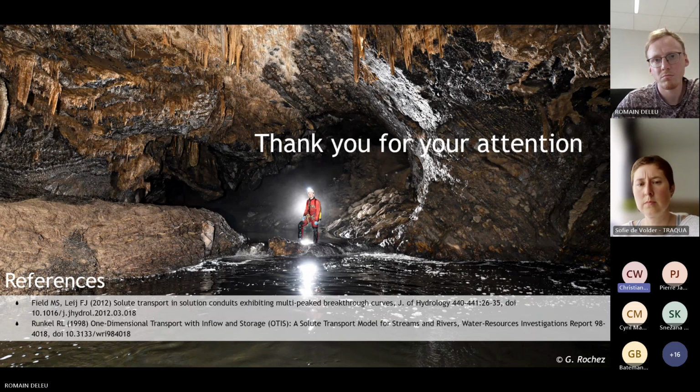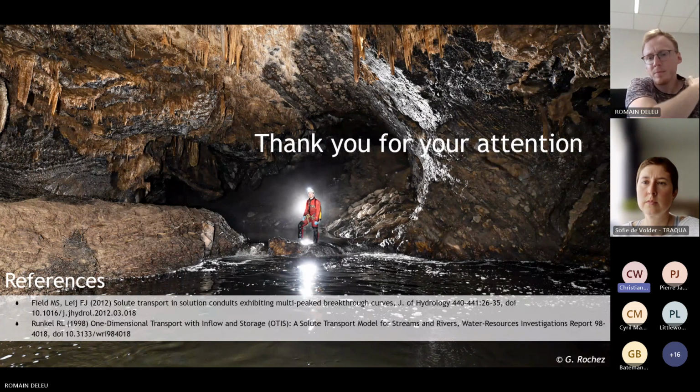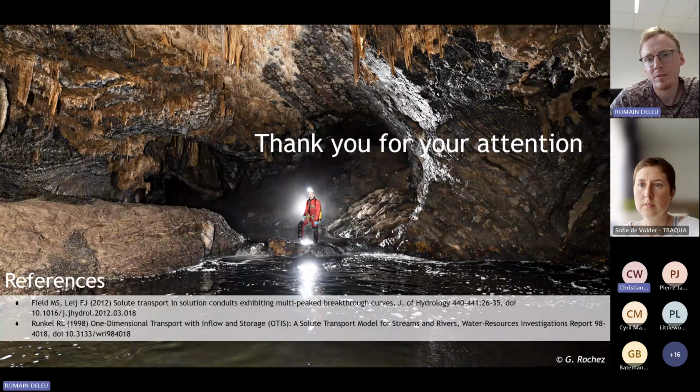Okay. Yeah, we have similar issues in the mining environment, and what we are using exclusively is the salt tracer dilution method, because for the salt tracer dilution method, the geometry of your channels does not matter at all. So that's probably something you might want to use in the future for measuring the flow. And you can also use your tracer, because you already have a tracer, the sodium fluorescein, for measuring your flow. That's relatively easy, because it's the same equation, just as an idea for the future.